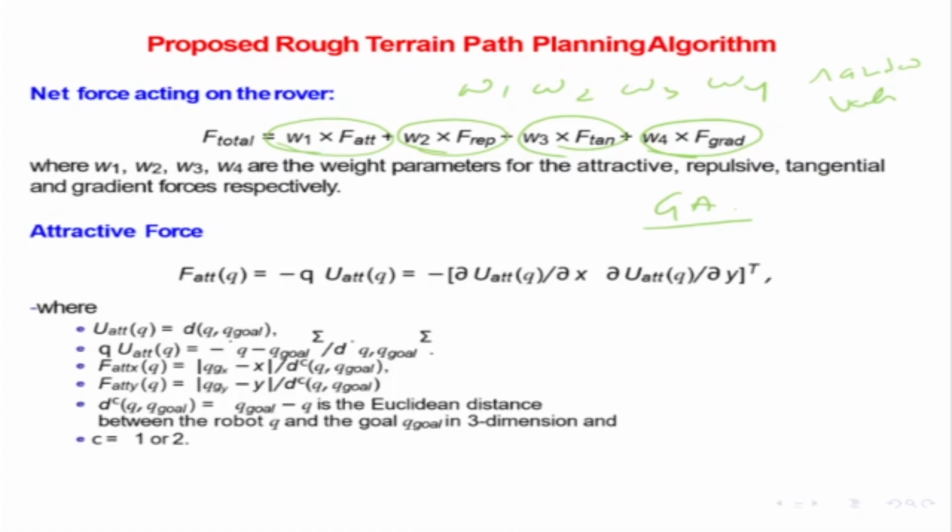evaluate a cost function. The cost function can be energy. Okay, it can be wheel velocities, omega squared, where omega is wheel velocities. Okay. So we can evaluate this or we can evaluate this and say which one gives us the least value. Okay, so optimal weights would mean vary W1, W2, W3, W4 and get minimum cost function.